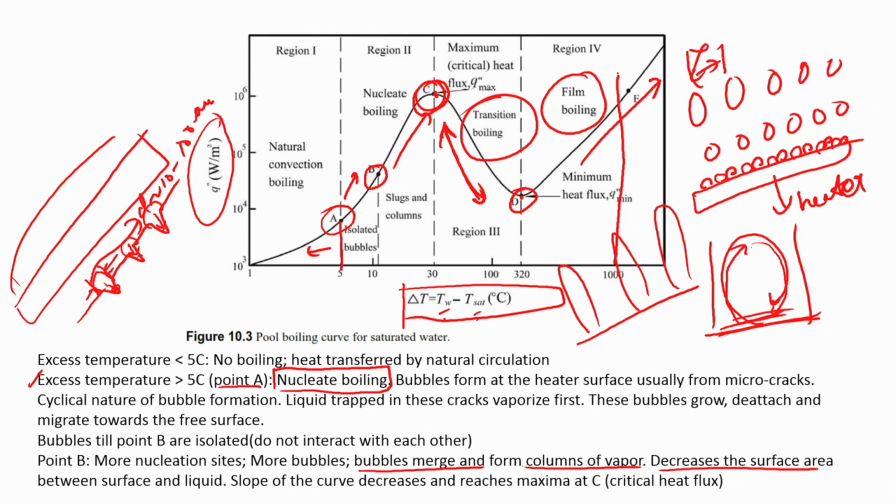In many of the cases, this boiling is done by putting in a heated wire within the liquid. So, this wire actually acts as the heated surface, and you get all the events like nucleation. What happens is that this wire actually melts, so it just detaches, and you have the end of the whole process. So, material integrity is one of the key factors when you look at that kind of a regime.